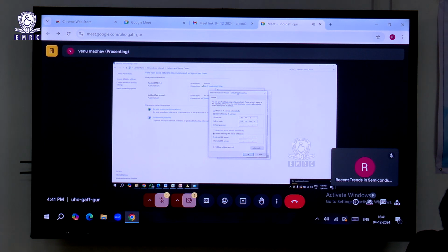What is happening right now is my board is going to act as a system of its own, and I am trying to access an application on this board using something similar to an FTP server. In order to use a server, you need to be in the range of that server. So we need to assign our Ethernet IP in the range of the board. How do we do that?